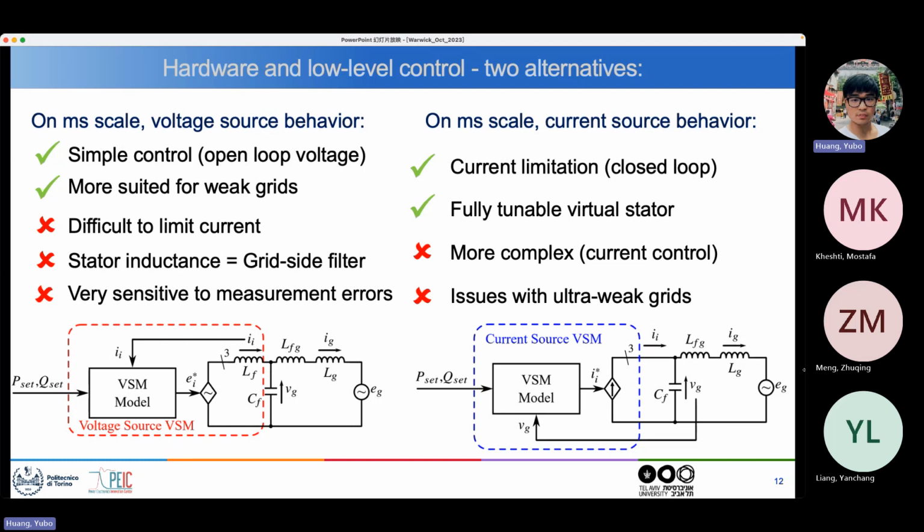So, by contrast, if the parameters are correctly chosen for this fifth order system, then the system becomes almost globally asymptotically stable. Now, this is a mathematical concept. It means that no matter from what initial state we start, there is a set of initial states from which it will converge to equilibrium. And the complement of this set has measure zero, which means that practically you will never be there. So it's an almost sure stability.